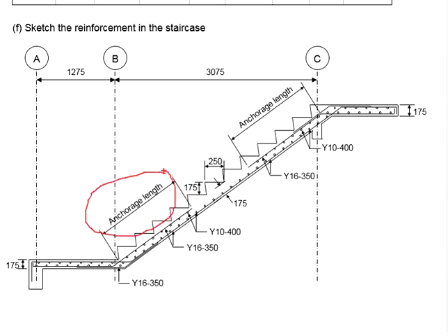Same goes to this. The 50 times the bar diameter will be towards the longitudinal directions of the reinforcement, as you are going to expect the reinforcement to be subjected to tension while resisting the moment at the support.